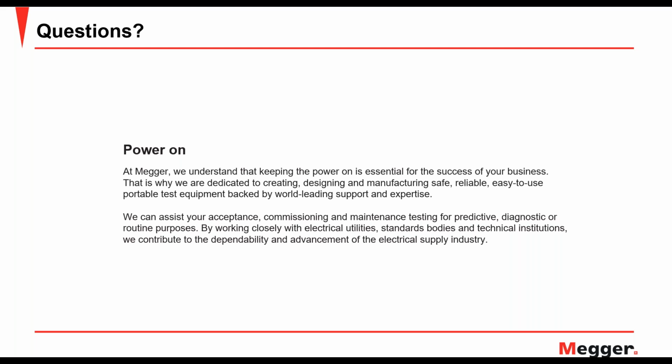So that would be my recommendation if you're testing. I would look at what kind of winding voltages I am dealing with. In those cases, I think you would really appreciate the value of looking at admittance, or conversely, the impedance plot, which does the mirror image of it. Both would be much sharper results to look at in those cases, and give you the ability to catch more changes from previous in the event you had some kind of a mechanical problem with the transformer.